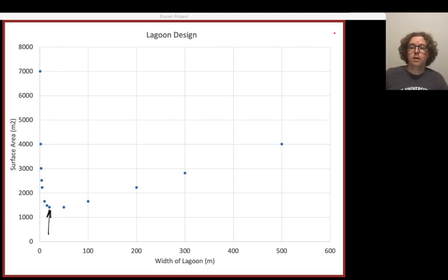Okay, so the goal of this example was really to help push us to thinking about CSTRs, continue working through our mass balance problems, and see how we can take that mass balance equation that we've been using to analyze CSTRs and operationalize it, or use it to design something that we might be interested in.